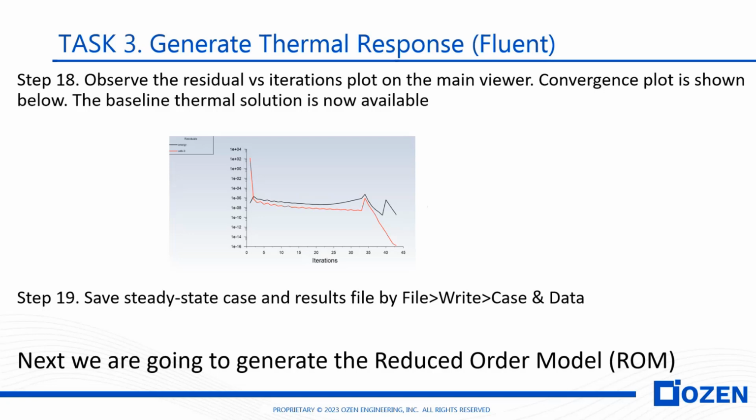We now have built our module battery model inside Fluent. And the next step is to generate the reduced order model from Fluent to be used in TwinBuilder.